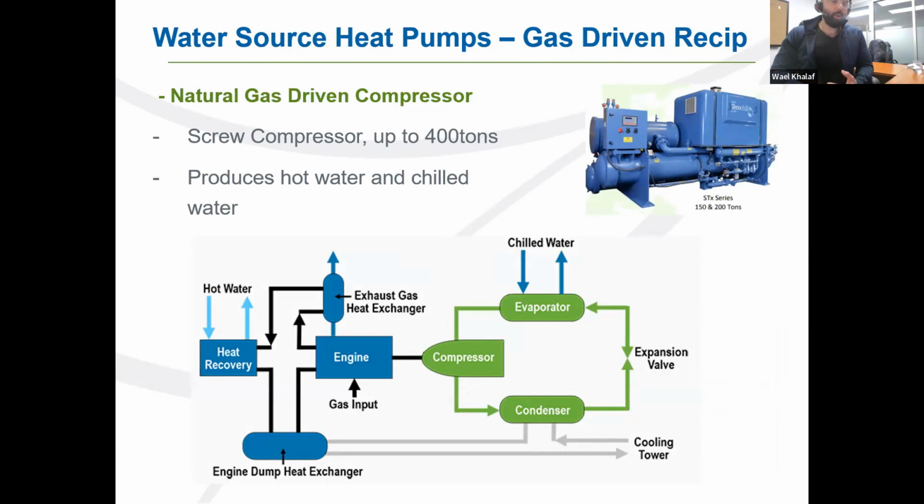And in terms of the hot water production, again, I can get my production from the condenser, but also I have a hot water jacket that covers the muffler of this gas engine and extracts that energy, and then I can reject it into a hot water loop. Or if I want to just reject it to a cooling tower, that works as well if I don't have any use for the hot water.